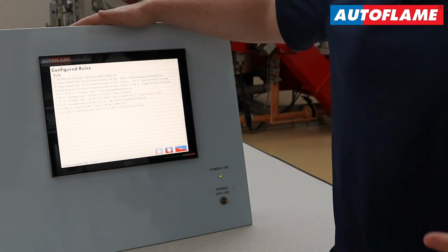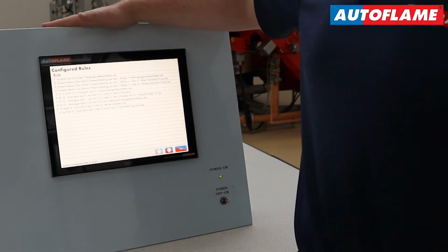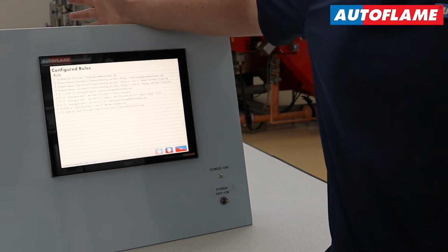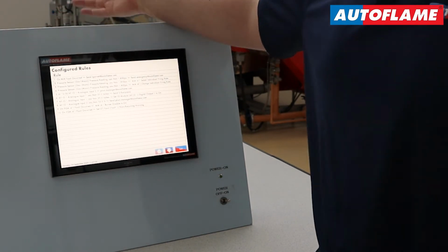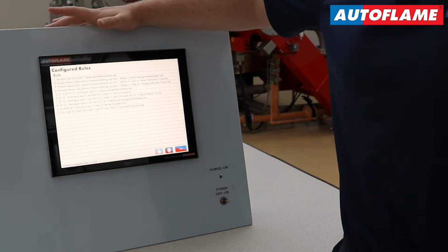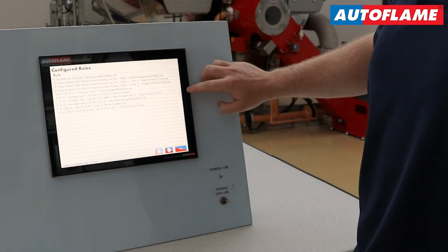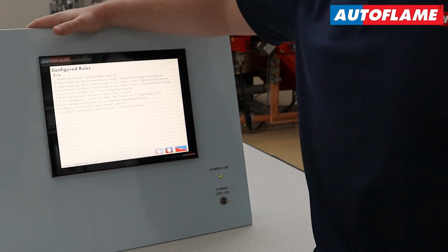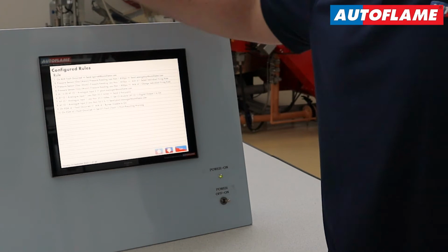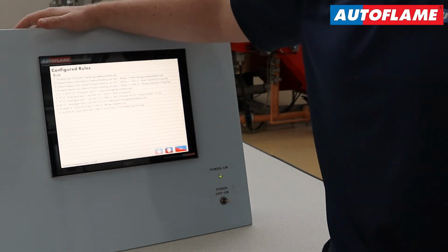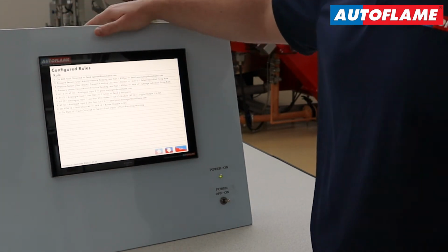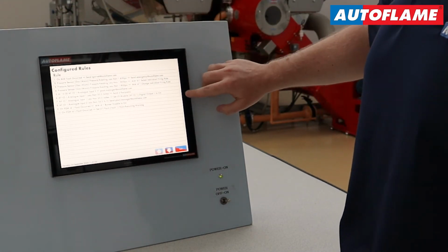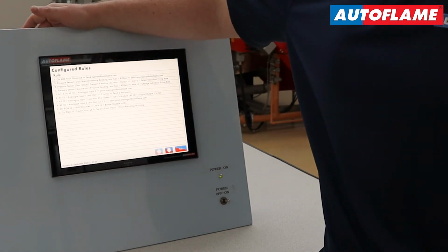I'm going to send an email to 2 recipients, in this case myself and the plant manager. I'm also going to energize digital output 1. So this could energize a relay to bring on a feed water pump for that DA tank. Now number 8 is for my oil tank again, so this is my analog input 2. Maybe I've got a level sensing device in there, some kind of device that can give me an analog input. So when that reaches less than 35%, I'm again going to send an email to the plant manager.